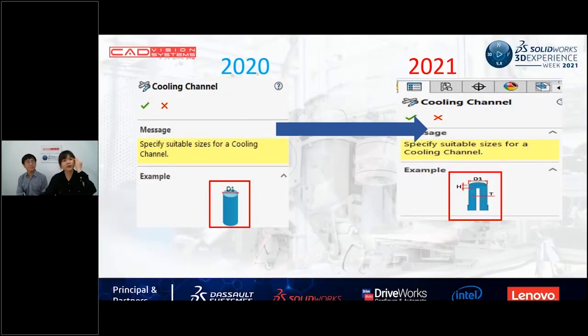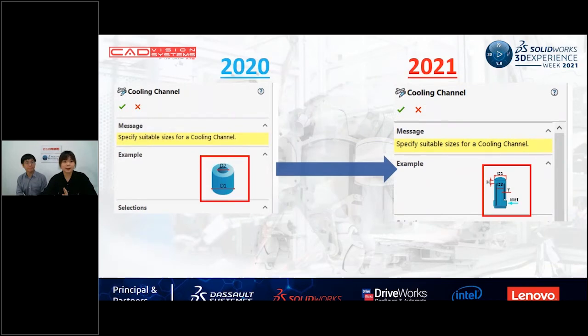So for the baffle, you can see from this screen that a blade was inserted into a channel to split a flow, which is here. And for the bubbler, an inner tube will replace the blades, which is like this.